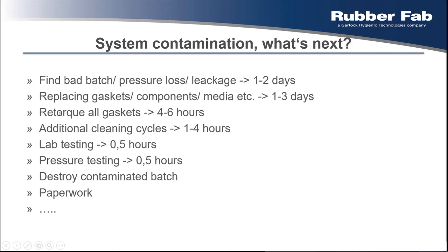Later on, with most gaskets, you then have to retorque all gaskets after pressure tests, after letting the system cool down again. Let's say it takes a couple of hours only. You again have to clean your system and start the sterilization process when you replace components and open the system. Then you want to validate your process, and if you're lucky and you have automated validation processes or an in-house laboratory, this might actually be quite fast. But again, no guarantee on the times. They may be shorter or longer depending on the capabilities of the manufacturer.